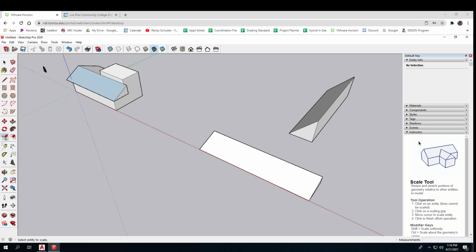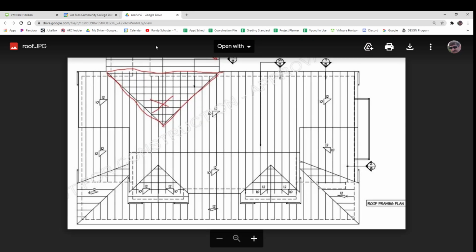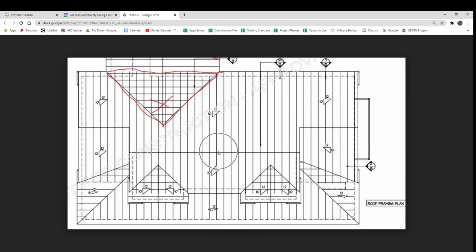Okay, did that make sense? You're essentially going to make one roof, your 10 on 12 main roof, that's your whole entire building. So people need to be able to see what I'm talking about here. You're going to make this whole 10 by 12 roof, and it's one entire roof. Okay, 10 on 12, this whole shape that I'm showing you. So you're going to make that roof with that center line 10 on 12.